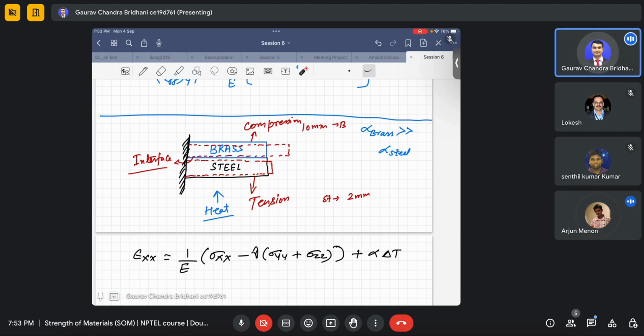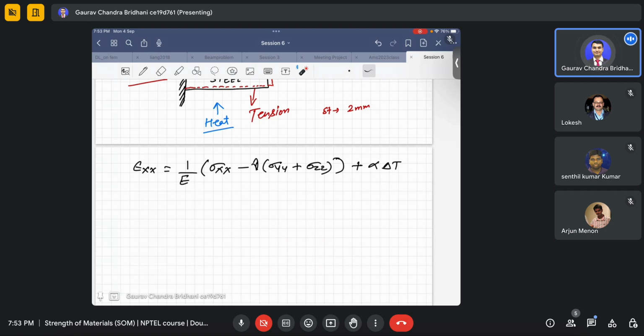The best example of this compatibility of strain is our reinforced concrete beam. You can visualize in another sense what is happening in our concrete beams. There is a compatibility of strain between the surface of the rebars and the concrete attached to that surface. That is an assumption, but that's how we do everything, whether working stress method or limit state method or anything like that. We say that there is a compatibility between them.